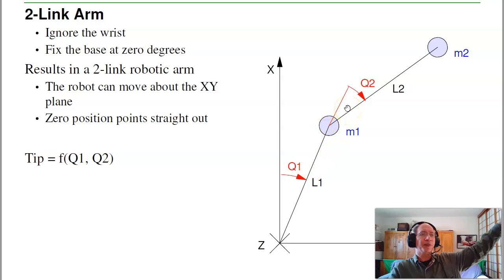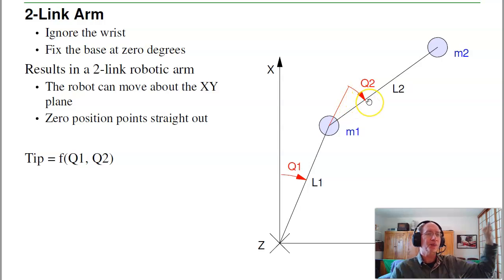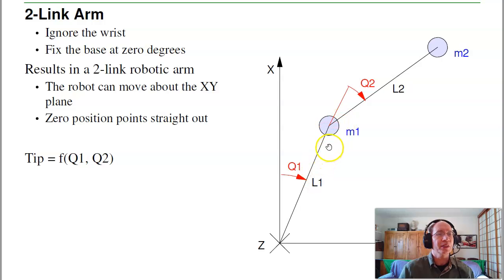Figure if I lock my elbow and turn my shoulder, the motor attached to the elbow hasn't moved. But the angle relative to the Earth reference frame changes with the first link. If, on the other hand, I move the second link relative to the first link, that's the motor turning, that's your q2. So typically in robotics, every link is relative to the previous link. So q2 is the angle of L2 relative to the angle of q1.